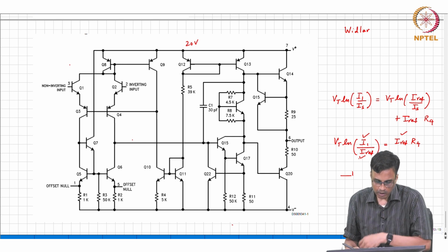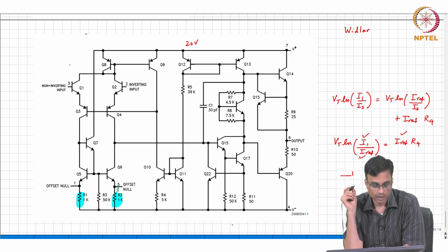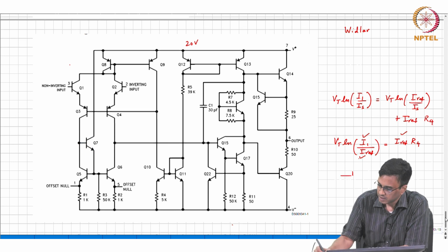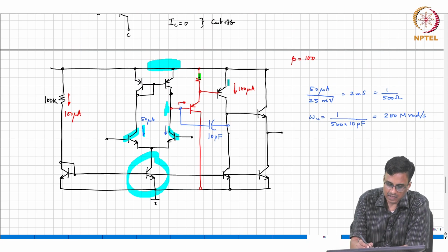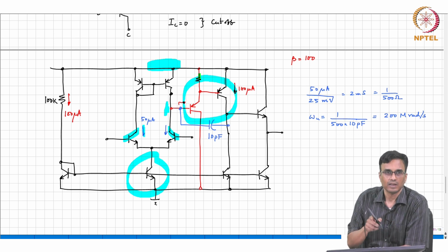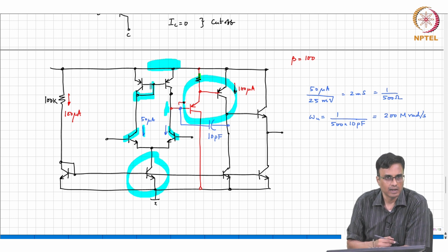All right. So, this part makes sense. Now, for the time being, just assume that these guys are short circuits. They are very small resistors anyways. So, the output of Q6, remember that in our diagram the second stage is going to load the first stage, and therefore we need a VCVS, and for the active load we simply short the base and the collector.